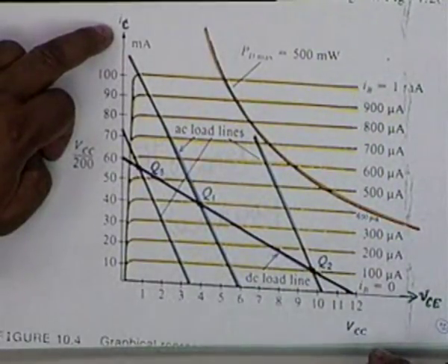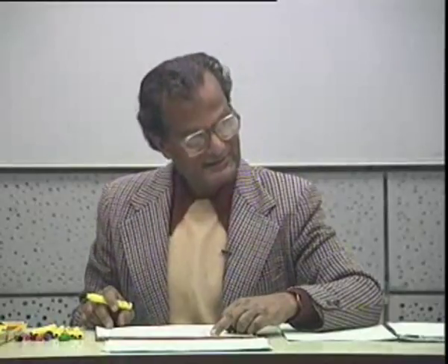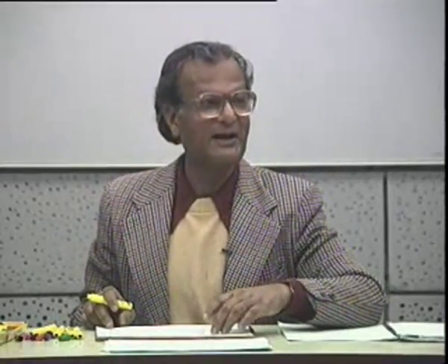So how do we calculate this power dissipation of the transistor? Is it simply VCE into IC? It is VCE times IC plus VBE times IB, but normally IB is beta times less, about 100 times, and therefore that dissipation is negligible compared to the collector junction dissipation.